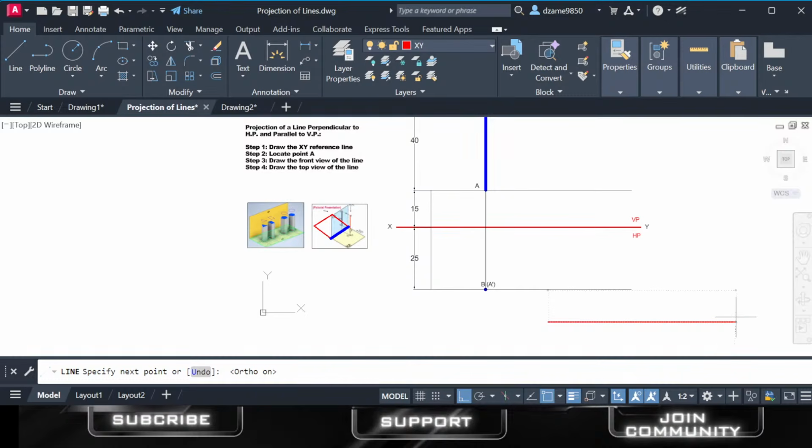You can see here, check closely, AutoCAD is marking it as 74. As I move backward, it's changing the dimensions, and at any given time it's very accurate. You can increase the decimal points. If you want 50 millimeters, type 50 and press enter, or right click to enter. That's it, and you have drawn that line.